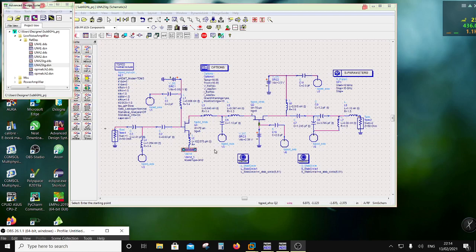Now the question is, this is a reference design. You can see the matching, and it is not by accident that the matching topology looks like this. This has been planned to be like this. Now the key here is the interstage cannot be a high pass. It has to be a low pass, because the current which flows through this common gate has to flow through this common source.